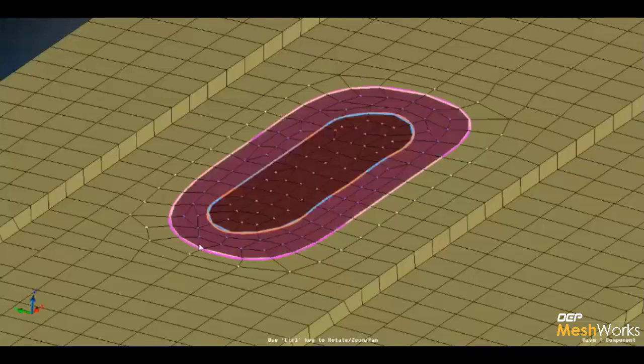For the fixed nodes I will just constrain with the edge of this particular bead. Same with the process. So I have selected this 1D as the fixed nodes and I will say accept and create a freeform offset. Once after creating the freeform offset, I will just link it. So the offset I will select to this, whatever we created now, and I will say accept and link it. Once after linking, the user will go to this translate function, tools,